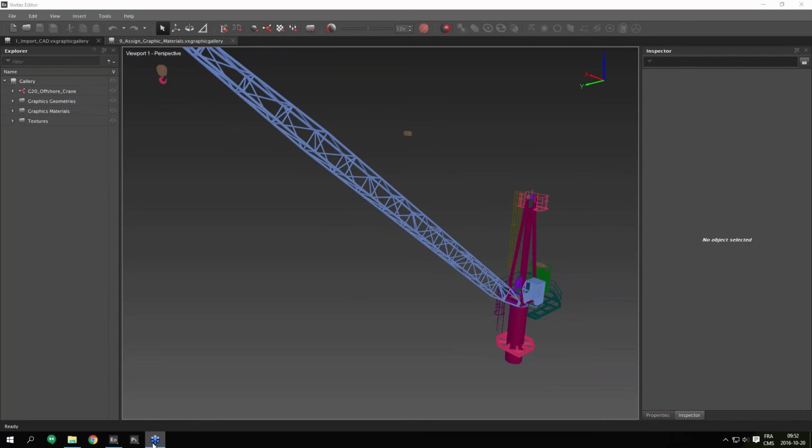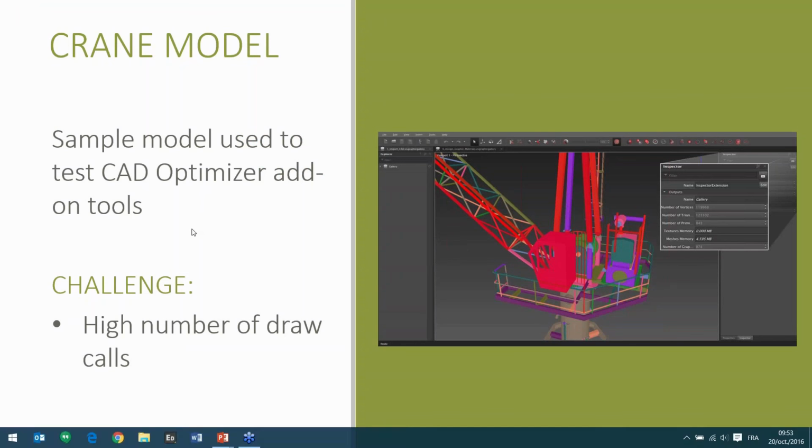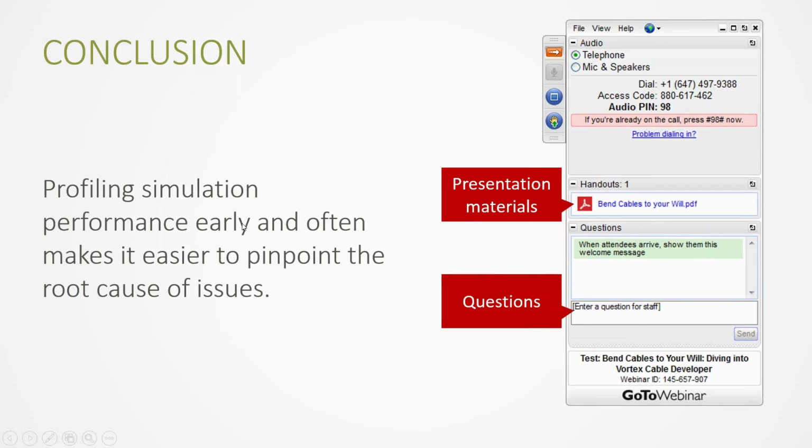Thank you, Marc-Alexandre. All right, so we're going to move on to the Q&A in a minute. Just before we close, I just want to come back on one of the big conclusions, the key takeaways from today's webinar. Profiling simulation performance is something that's best done early and often, because what you want to do is be able to compare performance before and after major changes. Profiling is something that cannot really be used in a vacuum because you're targeting obviously a certain frame rate, but exactly where you can go to optimize performance and where you have a budget to make those improvements, something that you'll see only by being able to look at historic data.